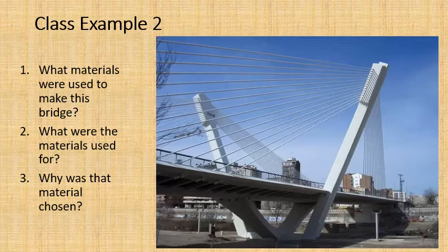We've got this big column where, what do we have with the column? We have with the column, probably it's reinforced concrete. Now, that's under compressive load, isn't it? The cables are pulling down onto the column and the ground is pushing up, so that column is being squeezed. Compressive force. Now, as I said in the last slide, with concrete, it's got great compressive strength, and that's why they chose it.